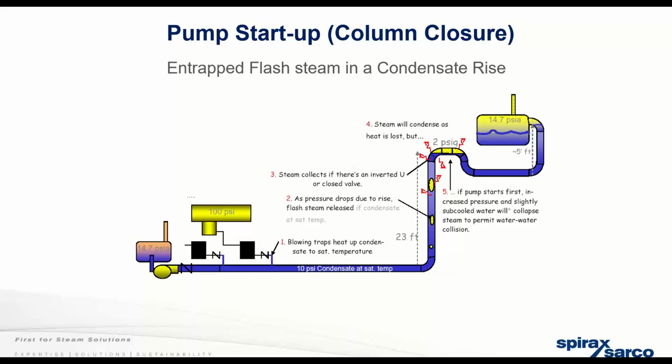So in this situation where we're pumping and discharging steam traps, we could get some slug flow, water hammer, and worst case, we could get some cavitation or bubble collapse. But just keep that in mind. Interesting one.